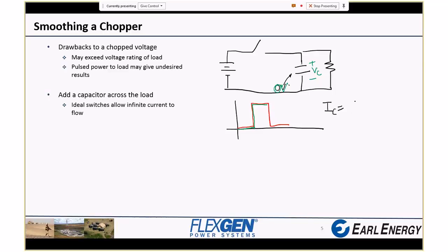So let's bring the capacitor equation back up. The switch closed in 0 time, so two things happened. At this instant, when the switch closed, we ended up with a dV, a change in voltage, of 10 volts. And since the switch closes in 0 time, dt was 0 seconds.